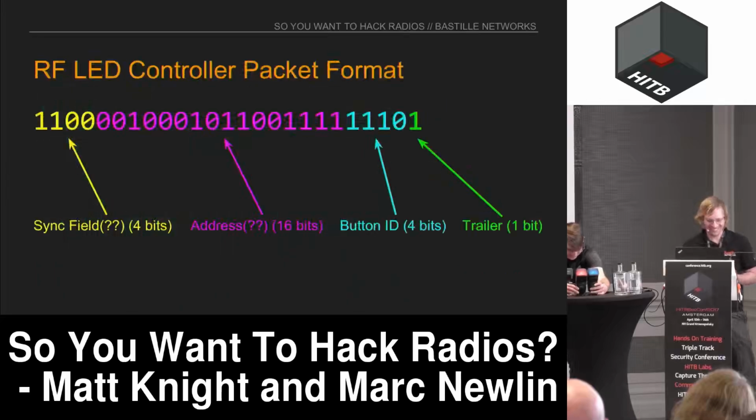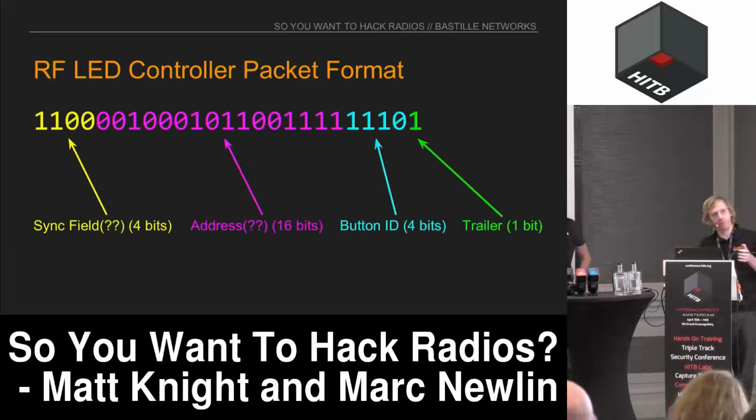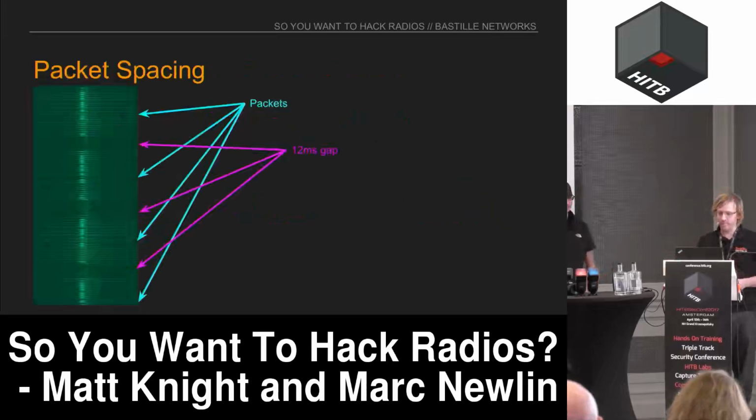So good. This is what our packet format looks like in bits for the LED controller. So we have a sync field and an address. The length of each are unknown, but we can assume these for the moment. Then we have a 4-bit ID for the actual button on the remote, and then this 1-bit trailer.